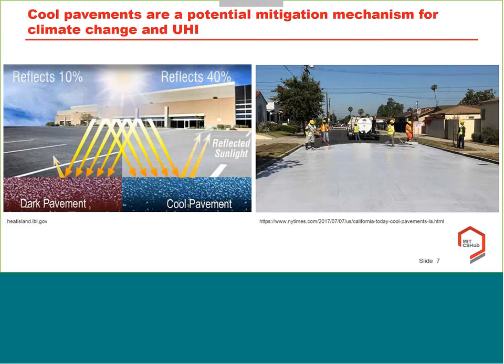Cool pavements, they've talked about basically different things, but essentially, generally that means they're pavements that have a higher albedo. That is, that they reflect more of the sunlight rather than absorb it. And there's a couple different ways you can do that. You can do that just by choosing different materials that naturally have a higher albedo, or as is shown on the right, you can also just coat darker albedo surfaces. So there are many different ways to do this. But because of that, there's no one single solution for a cool pavement.